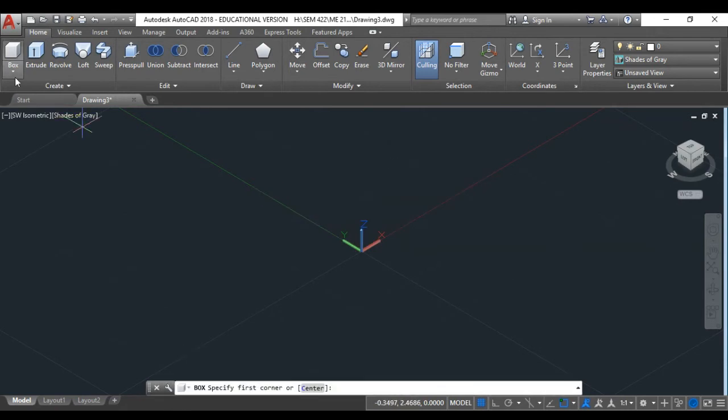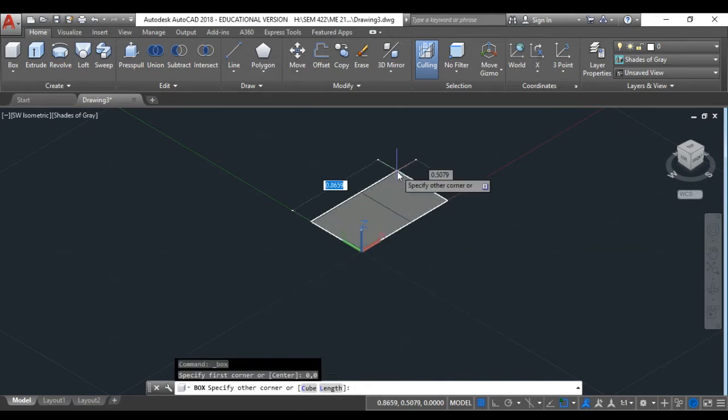What if I decided to just write down just 0 and 0? What will happen? Nothing will happen, because the program by default will add another 0. I'm sorry, the numlock is not working. Okay, here is the second 0, and that's it. Exactly, we started from the exact point, which means that voluntarily AutoCAD puts the third one as a 0.